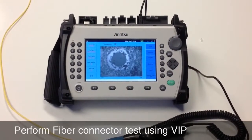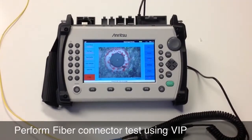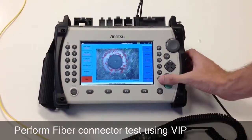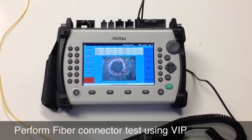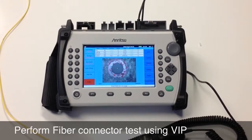Use the green start button to initialize the automatic analysis capture. It will determine whether the connector is passing or failing, and then you could bring up the analysis report to see exactly what areas are failing.